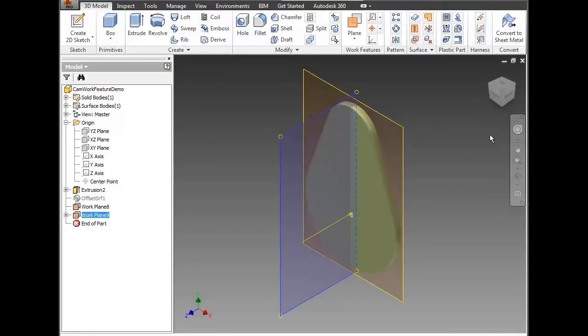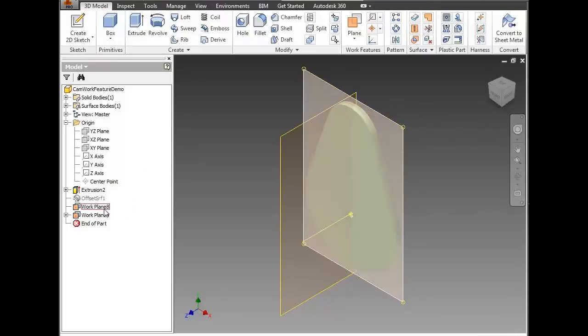Technically, it is important to remember this work plane, as do all work planes, extend infinitely in two directions. These work features will help you properly constrain your CAM in the CAM assembly. Note that you may toggle the visibility of any work feature on and off by right-clicking on the feature, either in the browser or in the graphics window, and choosing visibility.